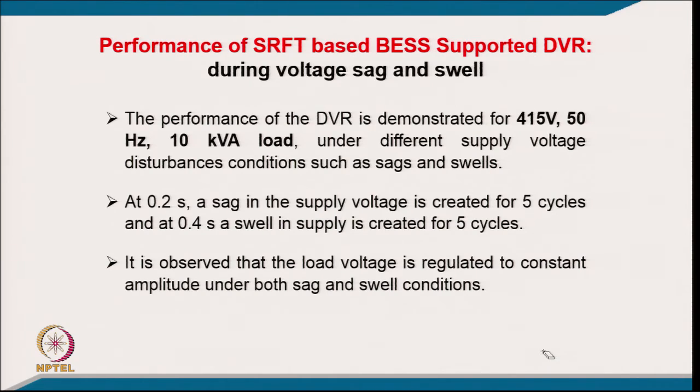Today we would like to discuss the modeling, simulation and performance of the dynamic voltage restorer. We would like to discuss first the performance of the synchronous rotating frame based DVR during voltage sag and swell. The performance of the DVR is demonstrated here for a 415 volt, 50 Hz, 10 kVA load under different supply voltage disturbance conditions, such as voltage sag and voltage swell. Of course, we will discuss in the time domain.